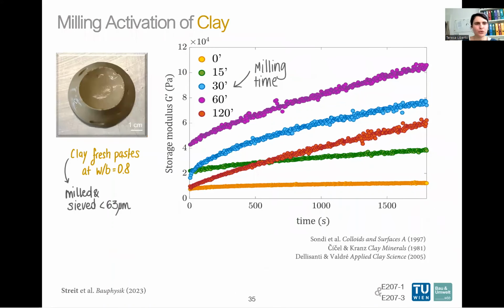Another example I want to show you is the milling activation of clay. So, as I showed you before in the schematic, raw clay alone is not reactive. So, one way to convince clay to be reactive is milling. And what we wanted to do is take raw clay, mill it several times and sieve it to have the same particle size distribution, and then make some fresh pastes at water to binder 0.8.